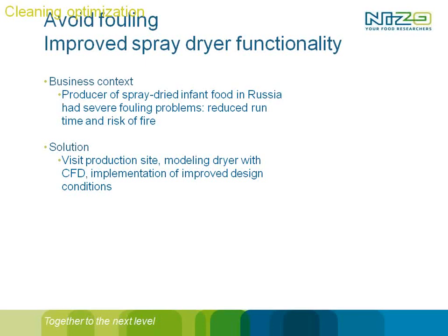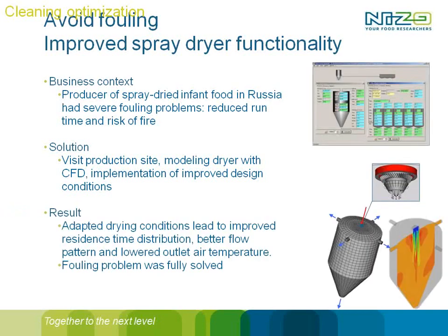Fouling can result in smoldering, so you can have lumps within your spray dryer which start to smolder, and the smoldering can result in explosion risks. So you should avoid fouling in the spray dryer. What we did, we visited the site, we modeled the spray dryer first within NISO Premia, then within the CFD, a computational fluid dynamics package, and there you can really model the whole airflow patterns inside the spray dryer. And we proposed improved conditions for the design of the air inlet.